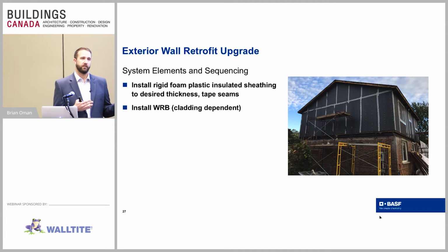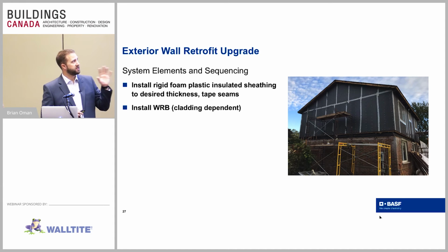If, in case maybe a building inspector doesn't want to look at that, or maybe we have a special consideration to take into consideration, maybe high winds or something like that, we can do inlet T-bracing or something like that. We can still provide the structural strength without having to change the design at all. So in this case, the expanded polystyrene is put onto the wall system.